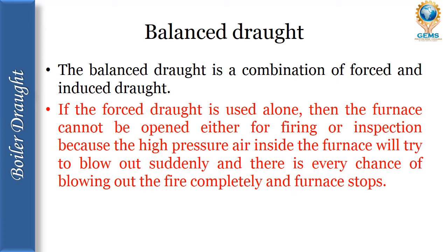In a forced draft system, the pressure inside the boiler system is maintained higher than the atmospheric pressure. So in any case, for inspection or any reason, if you open the boiler, suddenly the high pressure fire blows out from the boiler. So forced draft alone cannot be used.